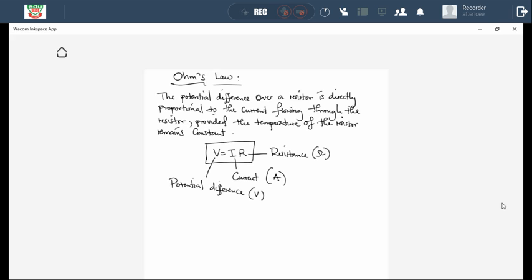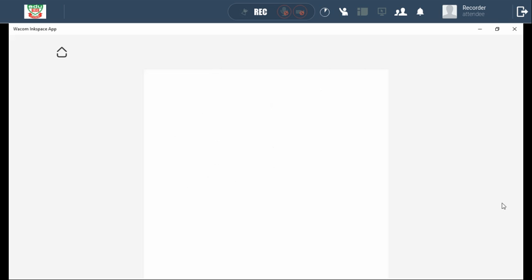Right. Now, in light of this Ohm's law formula, I want us to look at a circuit, the one that I promised, that has got a parallel connection and another resistor which will be connected in series, and we look at a few calculations on that. I'm going to draw a circuit diagram here and we do some calculations on it. So we have our power supply here, and do not forget that we are looking at conventional current, whereby current flows from the positive terminal to the negative terminal.